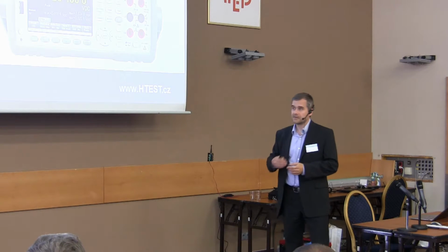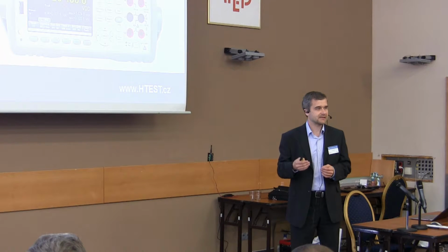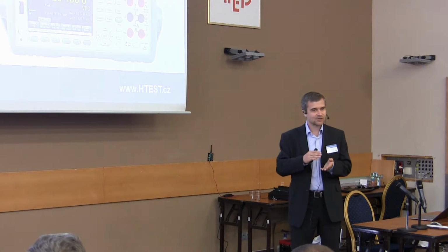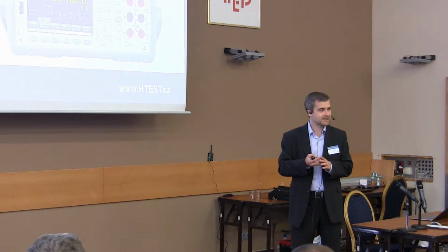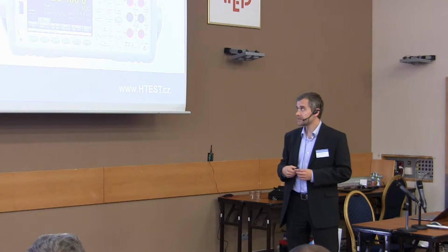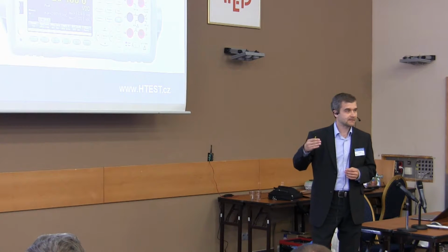In other words, when you are auto ranging, it changes the internal impedance, so it changes the measurement itself. To avoid this, you have to sample as quickly as possible to see all important transitions, and you have to set the range to fixed.